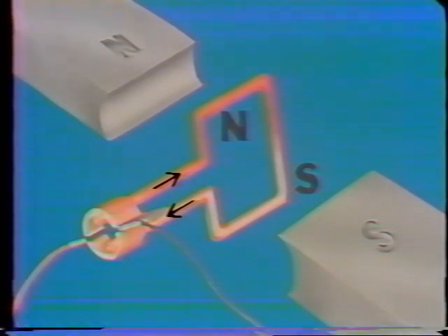At the point where the north pole of the permanent magnet and the south pole of the loop are exactly opposite, the motion stops, unless something changes. But at this instant, the commutator reverses the current in the loop. Thus, the north and south poles of the loop are reversed, and the motion continues. Now, you know what happens when two like poles of a magnet come together. In this case, the loop is repelled, so it continues to turn. The loop will keep on turning as long as the two magnetic fields interact this way.